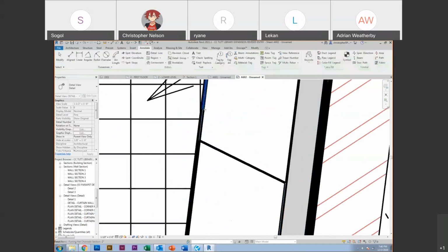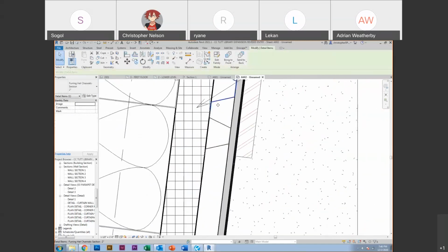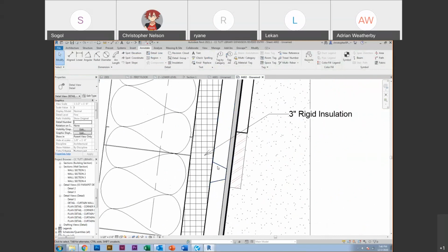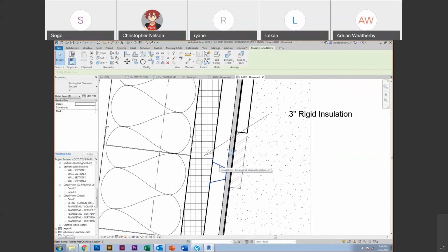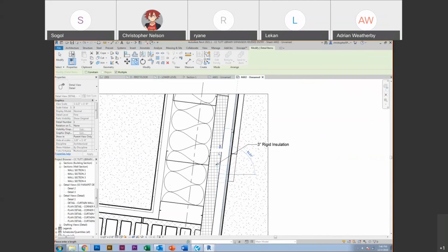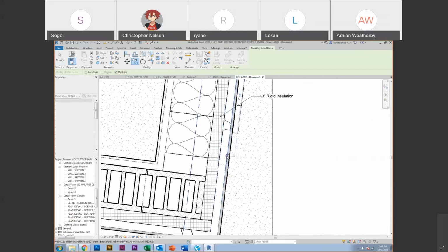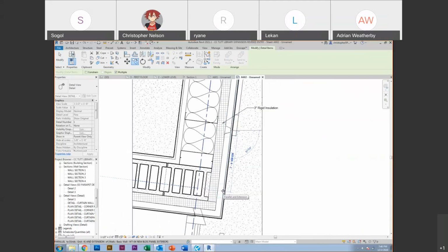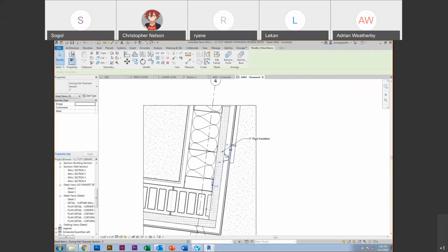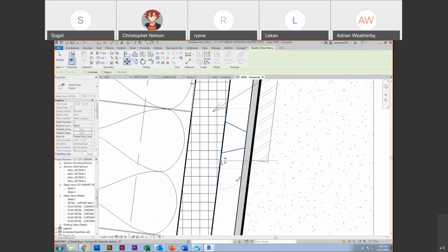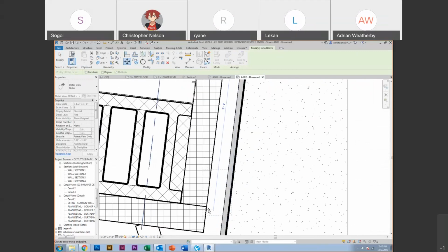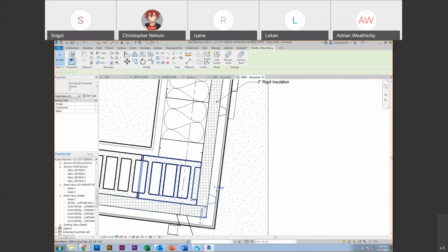But let's say I wanted one, but they're every so often. Usually they're every whatever the size of the panel is. So if you have a metal panel that's 2 foot by 2 foot, these little hangers that are holding onto your metal panels are probably going to be every 2 foot. So let's just say 2 feet. Let's just be smart about this. I'm going to pull the corner from the beginning, but pull it to the corner of your structure so it's anchored to the face of the CMU through the insulation.